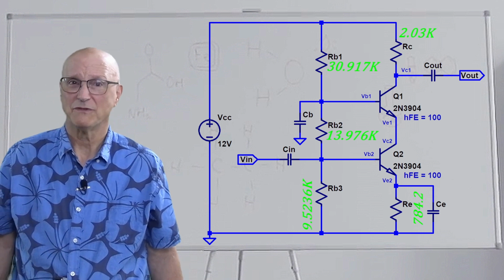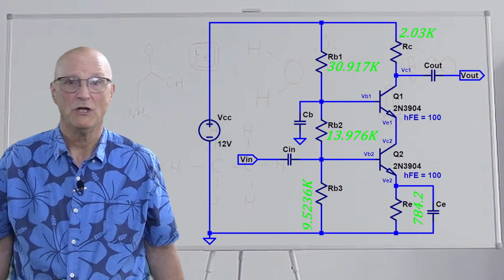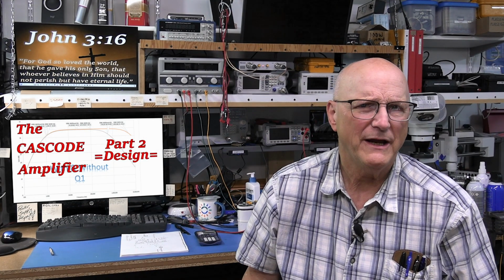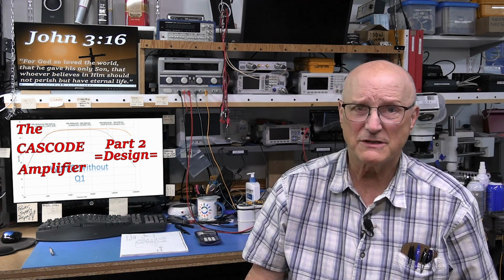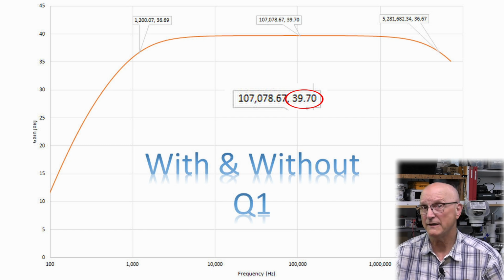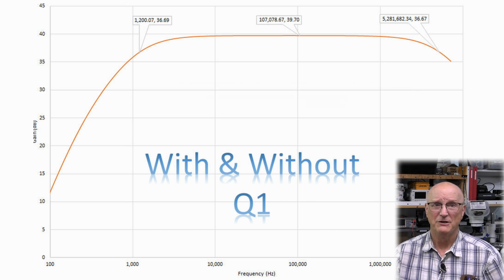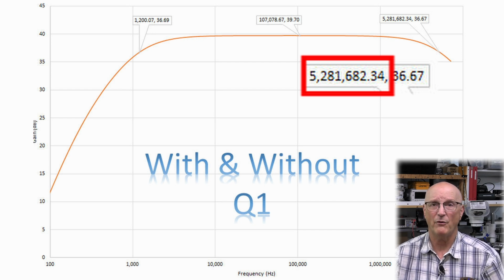But first, I will demonstrate the performance of this circuit through the use of an LTSpice simulation using all of these ideal calculated values. Well, I have created the circuit in LTSpice and simulated it. You can see the results of this simulation here. Notice that the maximum gain is 40 dB and the calculated gain was 41 dB. Well, not too bad. You can see here that the upper end minus 3 dB point is at 5.281 megahertz.